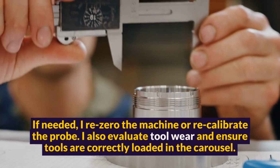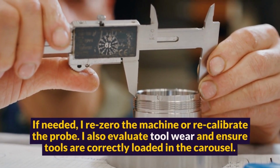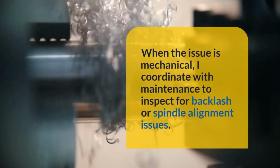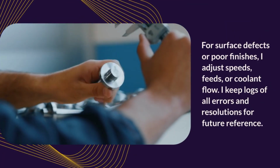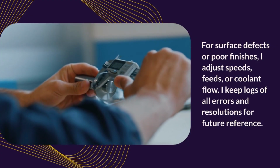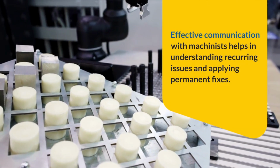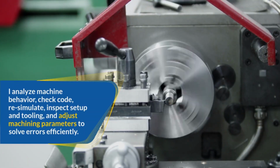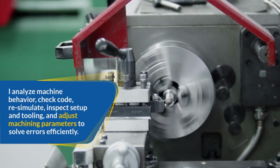If needed, I re-zero the machine or recalibrate the probe. I also evaluate tool wear and ensure tools are correctly loaded in the carousel. When the issue is mechanical, I coordinate with maintenance to inspect for backlash or spindle alignment issues. For surface defects or poor finishes, I adjust speeds, feeds, or coolant flow. I keep logs of all errors and resolutions for future reference. Effective communication with machinists helps in understanding recurring issues and applying permanent fixes. I analyze machine behavior, check code, resimulate, inspect setup and tooling, and adjust machining parameters to solve errors efficiently.